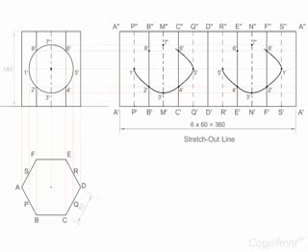After joining the above points by a smooth curve, we get the development of the lateral surface of the prism with the shape of the holes in it. So friends, here we have completed our example of the parallel line method. For practice, you can solve some more examples.